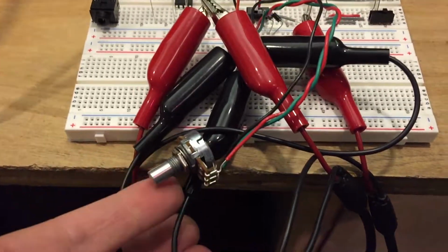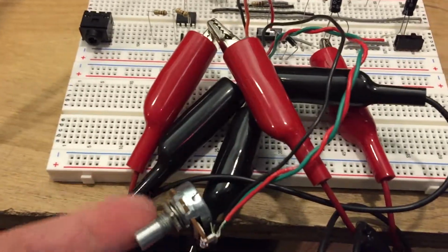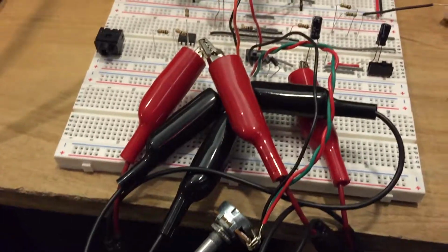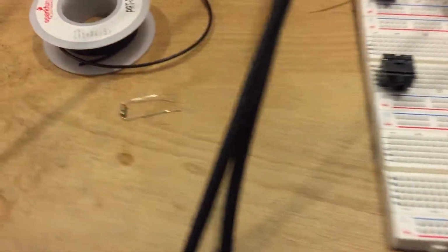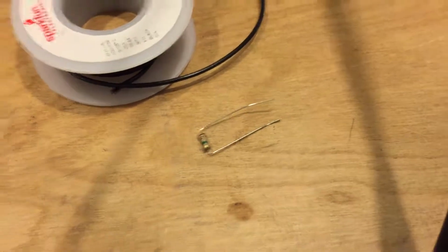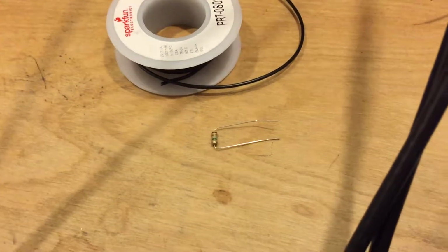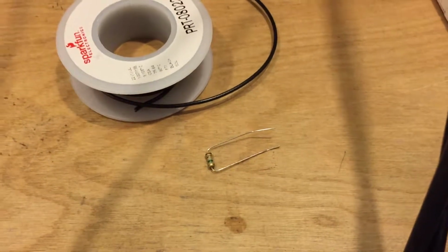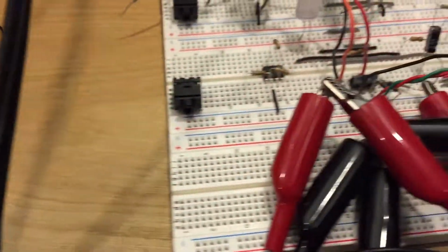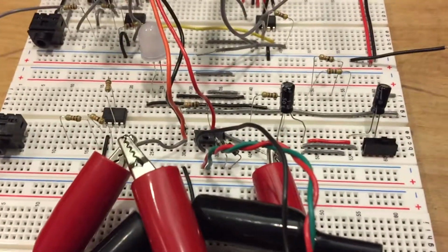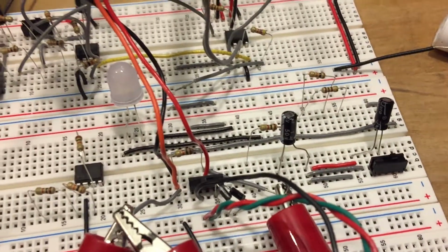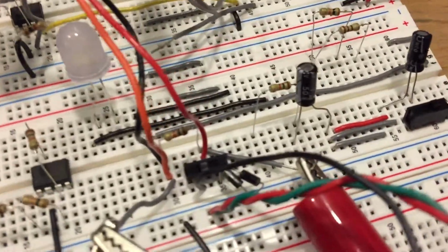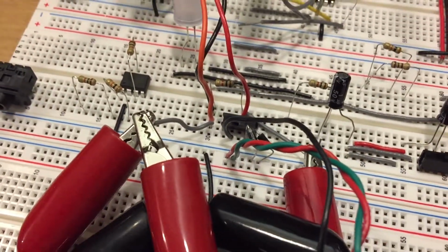So we want a very large resistor. The one I'm using right now is an audio taper 100K ohm. It doesn't have to be variable, but this allows me to tweak values. Before, I was actually using a 1 mega ohm resistor, and that works fine too. You simply wouldn't have any possibility of changing the amplitude of the wave. So it would just be a bypass, and you'd have to go to circuitry down the line for more adjustment. So let's see what this looks like in action.